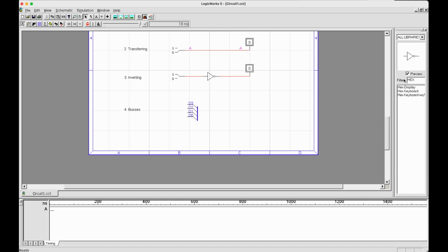For this example, I'm going to use my trusty hexadecimal keyboard to provide input. Let's say we want 4 bits of binary value to be transferred on a single wire instead of 4 separate wires through a long distance. On the receiving end, let's pretend that we need a hexadecimal display. Again, it is very important when you're using the hexadecimal display and the keyboard that you make sure the most significant digit is on top, over here. The most significant digit on a hexadecimal keyboard is on the same row as 0, 1, 2, 3. This is the least significant digit, C, D, E, F over here. For a hexadecimal display, the least significant digit is noted by the solid black dot over here.